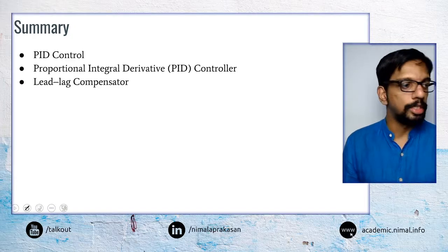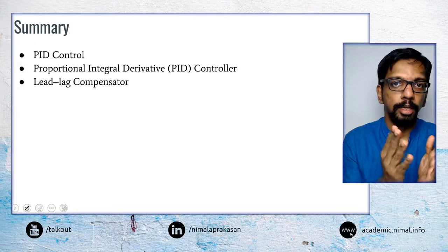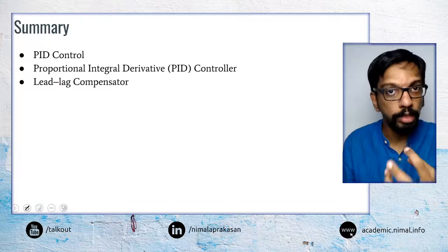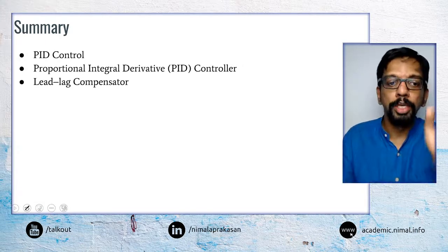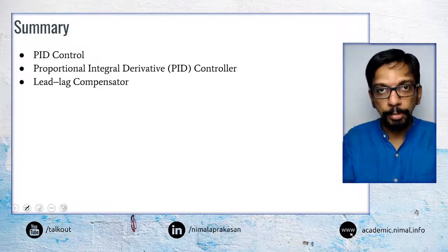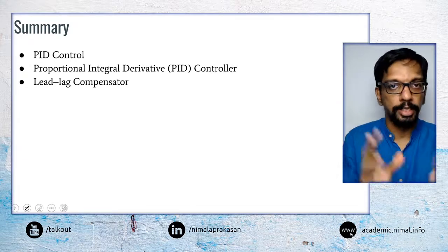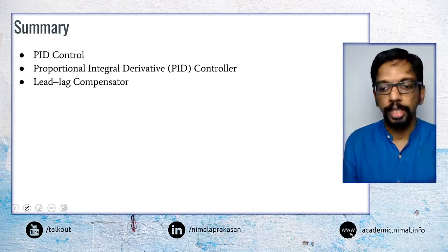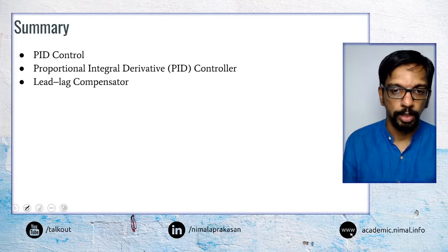So the main thing that we discussed today is PID controllers and how we can implement each of these components, what the importance of each of these components is, and why we use each of them. We also covered the importance of tuning the constant values, the K values, and how we can change them to achieve a combination of a PID control. We briefly touched upon the lead lag compensator, but as I said, the PID controller is the main focus of this course, and that is what we would be focusing on in terms of your project as well.